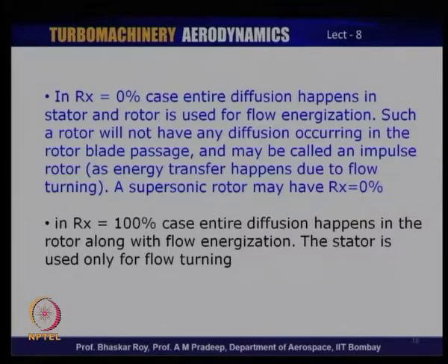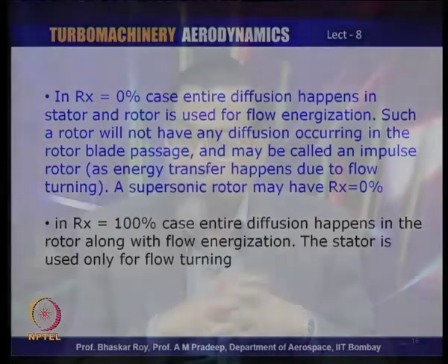Now, many supersonic rotors may have a degree of reaction of 0%. It is possible that subsonic rotors may also have it. One of the possibilities is the supersonic rotor, where the flow is supersonic through the rotor blades, and during that a lot of work transfer is accomplished. However, the diffusion is deferred to the stator, mainly because the rotor is busy transferring energy into the fluid.